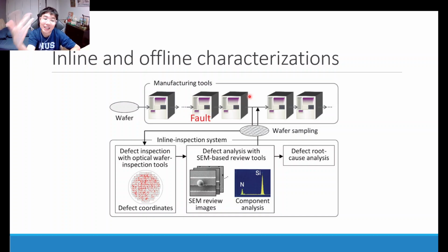So these are called inline inspection. One example is optical inspection, which I'll cover in the next video, that can for example count the number of particle contaminants on your wafer just after it finishes a step in one machine before going to the next machine. This is inline, and it's very important because it allows for detection between the various steps of your wafer fabrication.